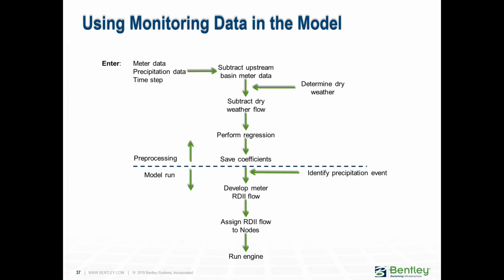Then, in the next step, to model the wet weather event, having the precipitation event, developing the RDII flow, and then assigning it to the nodes, you finally run the engine and get your model with both wet and dry weather flows.